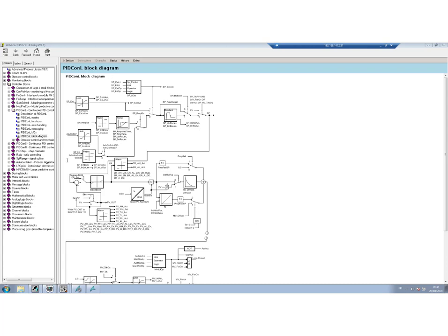Well, the top part here has to do with setpoint handling, and we'll come back to that later. Well, you have ramping of the setpoint, you can set gradient limitations and things like that. So here you have the setpoint coming in, and what is coming out over here is PV, right? If you have a problem with a measurement because you're working, for instance, on a sensor, you can use this input over here to take a simulated PV instead.